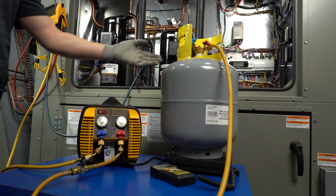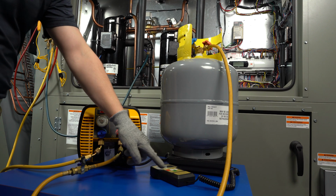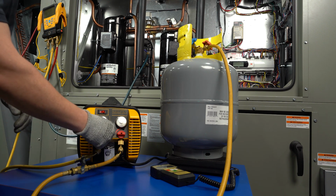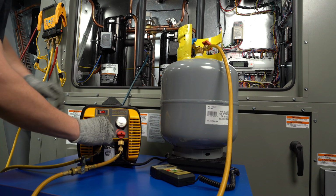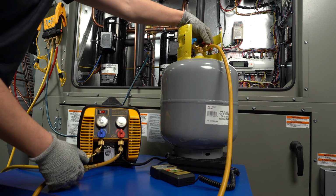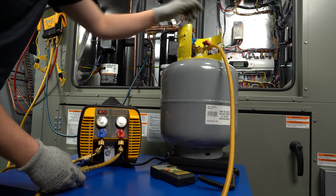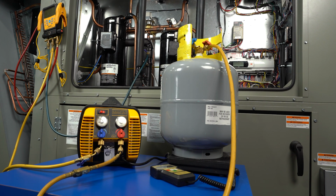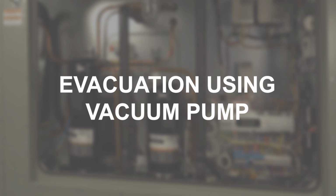Place the recovery cylinder on a scale and zero the scale. Turn on the recovery pump and wait until system pressure is near zero, which may take several hours. Do not allow recovery pump to pull the system into a vacuum if a leak exists. This will contaminate the refrigerant with air. The system can now be purged with nitrogen and is ready for service.